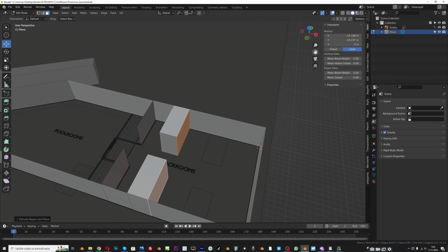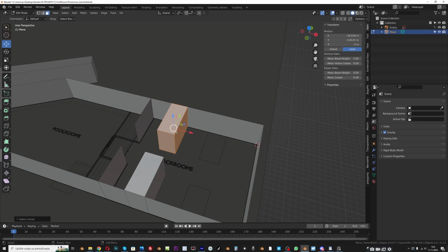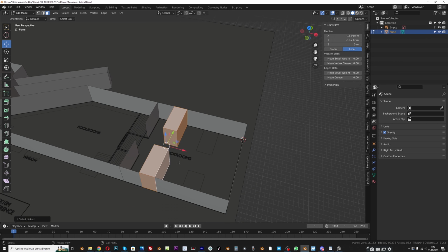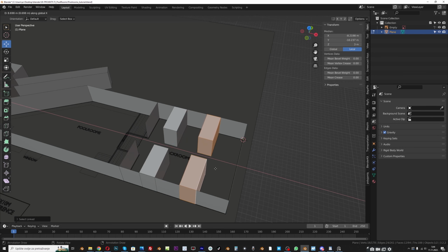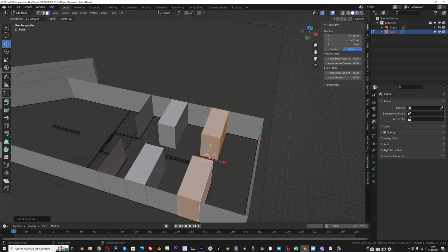And if you now press L over this part, we select the loose part. So L and L here, and now Shift D again and X for x-axis and move this to about here. Okay, I will press S and X to scale this a little on the x-axis and also these two parts.